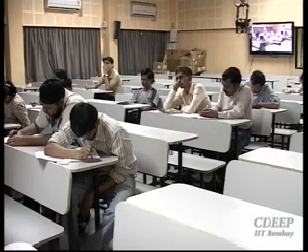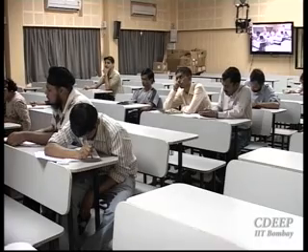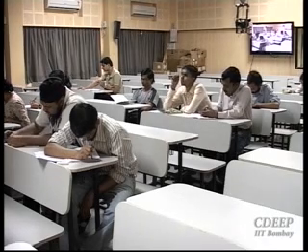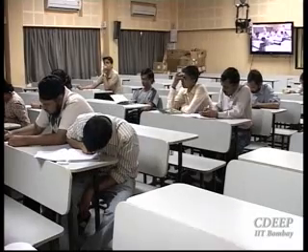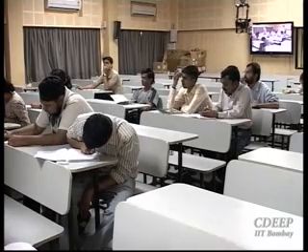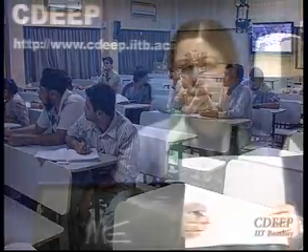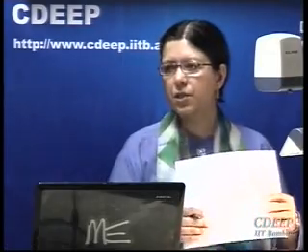However, as I mentioned last time, every time you are connecting to V full scale for charge distribution, you are spending energy. So you can look at Vinayak's paper as well as its references for different recently reported configurations of SAR ADC, which have looked at how they can make it more efficient with respect to energy.